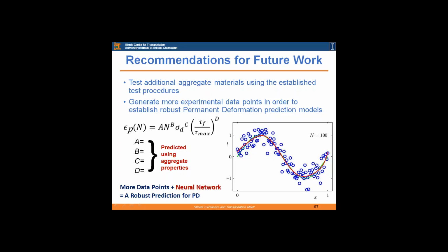And if you have the shear stress ratio alone, then at a given shear stress ratio, let's say of 0.5, you can actually have so many combinations of stress states in terms of sigma 3 and sigma D. So both of them need to be considered together in order to get good correlations. And that's why we think that stress is an indicator that will drive, let's say, sigma D or tau F. They are both stress terms.